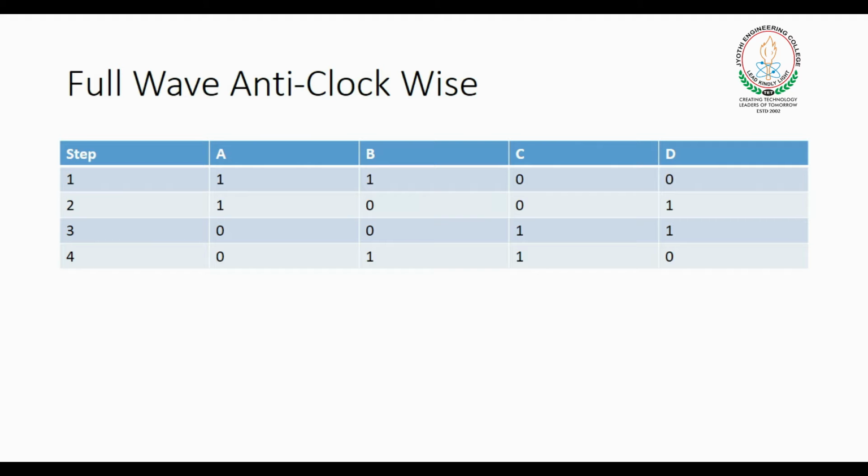Similarly, for anti-clockwise rotation, the first step should be 1 1 0 0. Then the second step is 1 0 0 1. Then the third one is 0 0 1 1. Finally 0 1 1 0.